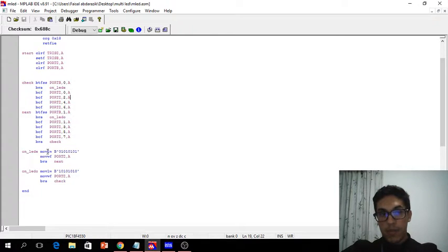So what is this binary doing? Quite easy. It's just in order. You will set up in order all LEDs. That means 01010101. As you can see in our device, the order of LEDs started from 1, 2, 3, 4, 5 until 8. So that's what's gonna happen. It means that the first LED is going to be off, second LED is on, third LED is off, fourth LED is on. Whenever it's 1, that means that LED is going to be on.